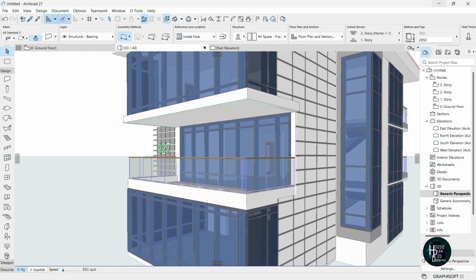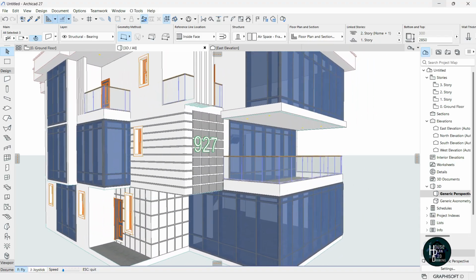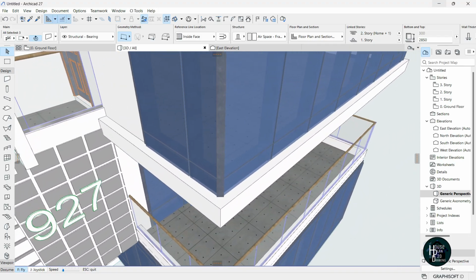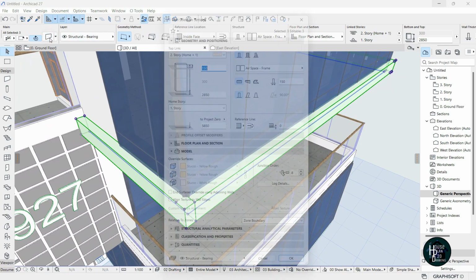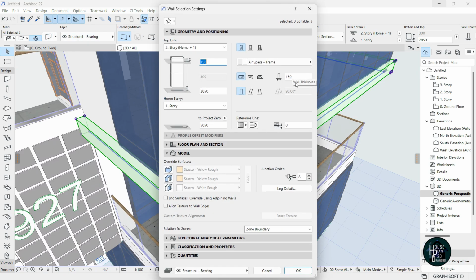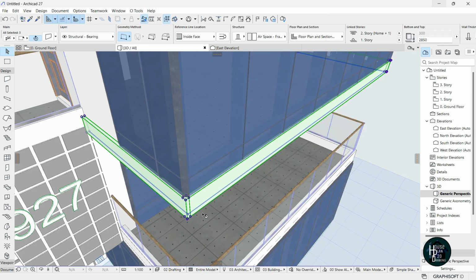Alright, so that's going to come outside a little bit. So you're going to have a design coming outside like this. So press escape again, come to this side here, click on the settings dialog here, come to this side here, change the thickness to be around, say something around 50, click enter. Okay, so you're going to have the design shown like that.